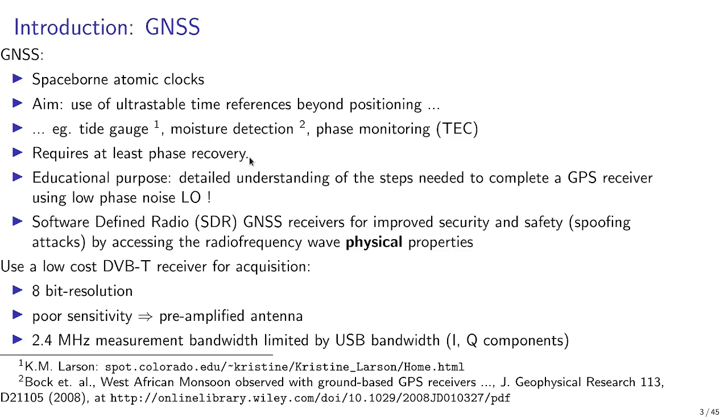Many of these applications require phase recovery, but we will see that the code already encodes multiple pieces of information that are useful for an educational purpose, where we identify each and every step of the GPS decoder. But even from a security perspective, analyzing the raw radio frequency data is the only way of detecting spoofing and mitigating spoofing and jamming by canceling the interfering source by null steering. So the radio frequency analysis using software-defined radio allows for recovering the genuine signal and canceling the jamming source.